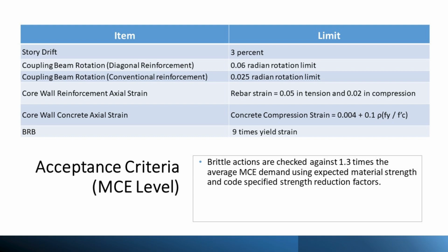And if you change something in the structure, this number will change. And if you change the earthquake, this number will change. Which means that now we have a relationship between design decision and the earthquake level and the final performance. It's not just that you follow something and you don't know what really happened. So it brings me back to what I said previously, that if you change the spacing of the stirrups in a column, you should see some change here in these numbers.